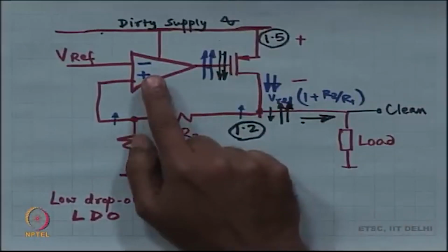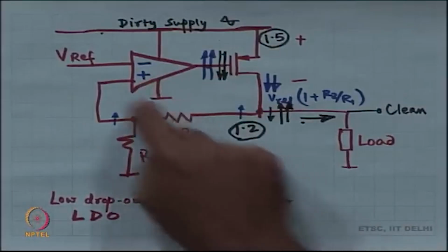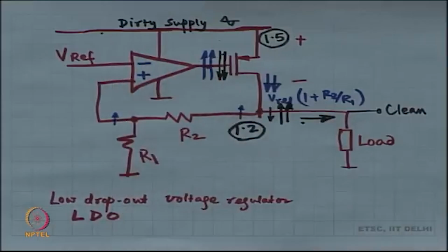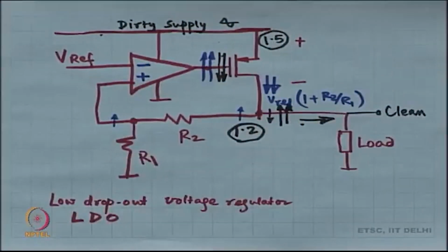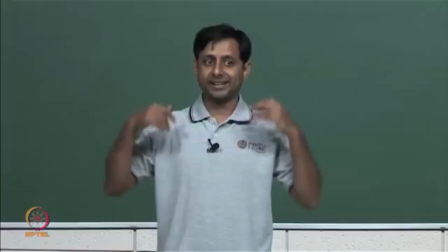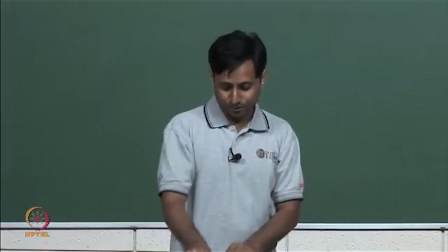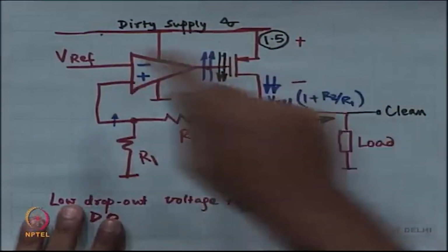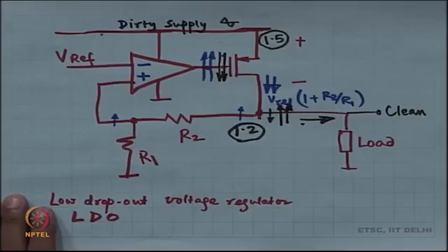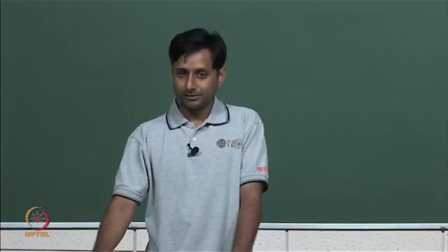However, over here if this is a 2-pole system, the net structure is actually 3 poles. It is as if you have got a 3-pole amplifier and then you are placing it in feedback. All right. Now, when you do that, you have to compensate the 3-pole amplifier and not the 2-pole. If you just compensate this 2-pole or original amplifier, it is not going to be good enough. You have to compensate this entire 3-pole system. Okay. So, this is going to be much harder.